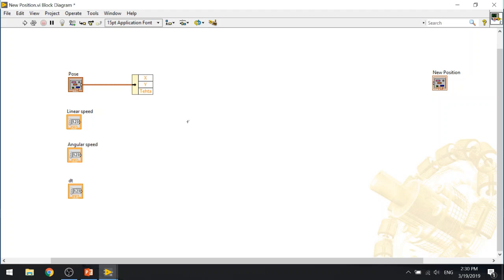3 robot coordinates, and because the robot has only linear and angular speed, we can calculate with that, from the local to the global coordinate system, how much in each coordinate axis the robot travels.